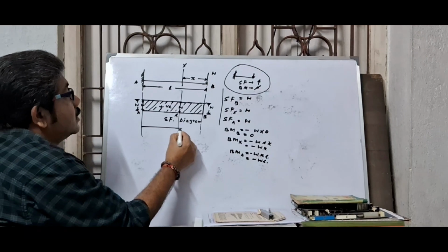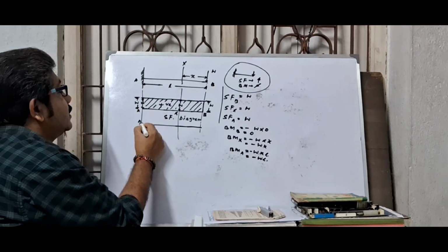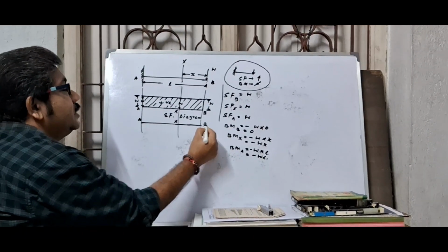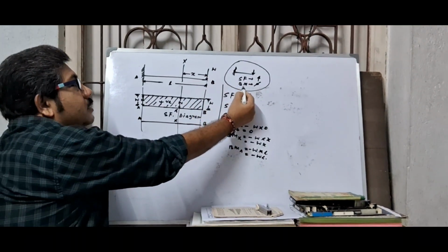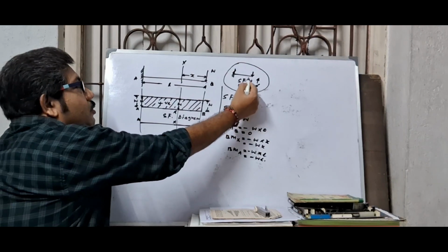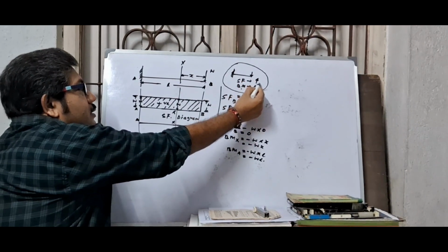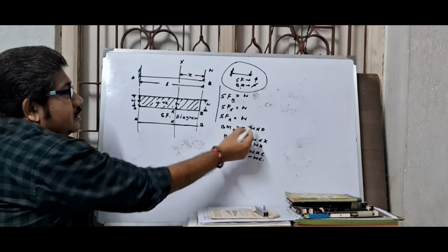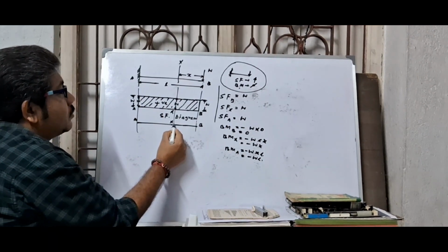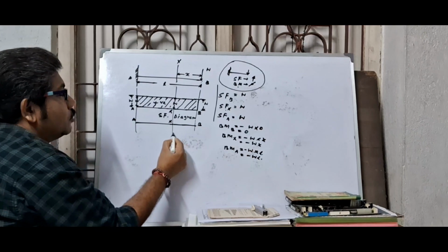So here it is the reference line AXB. And look here. This is the bending moment for a point load. This is an inclined straight line. At point B, this is 0. At point X, this is Wx.